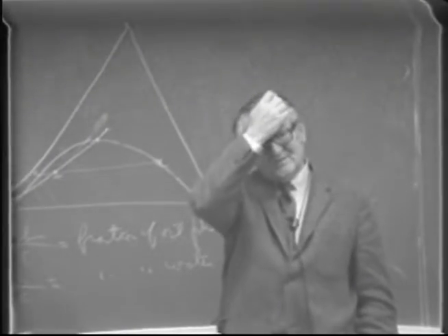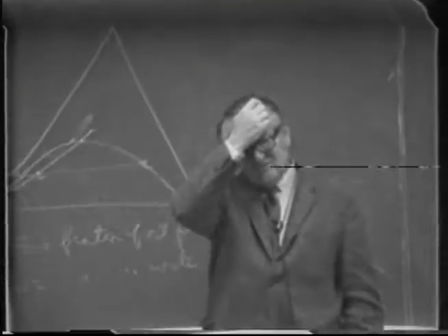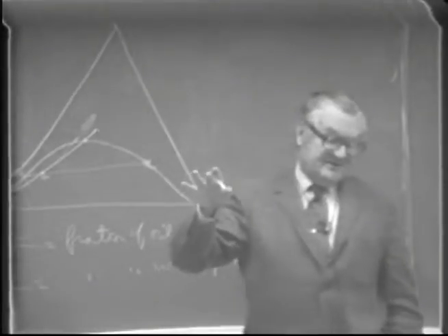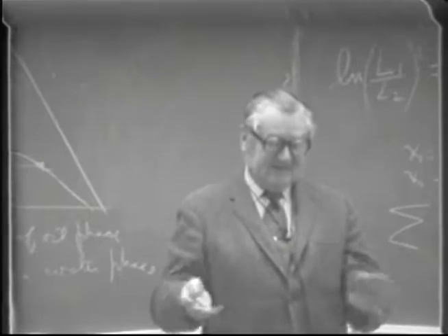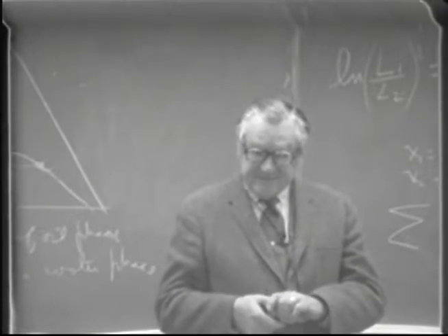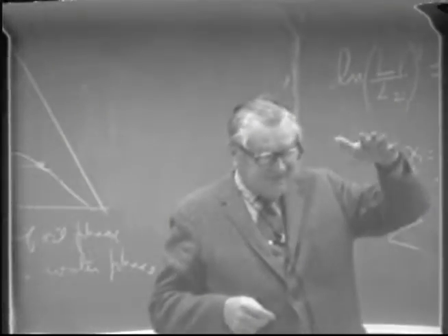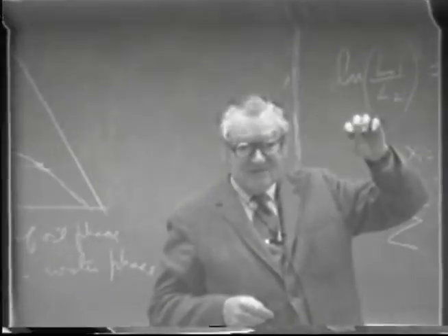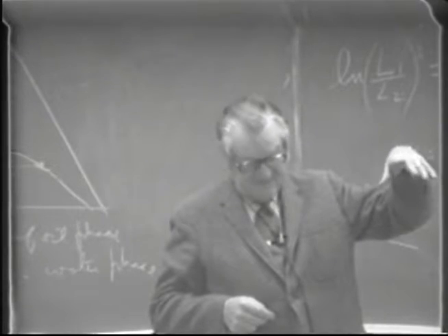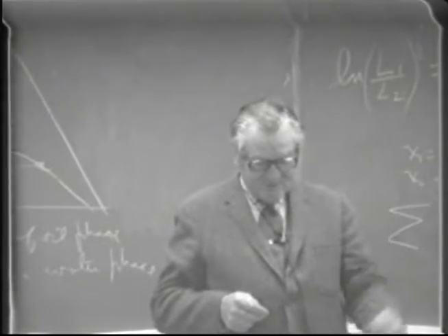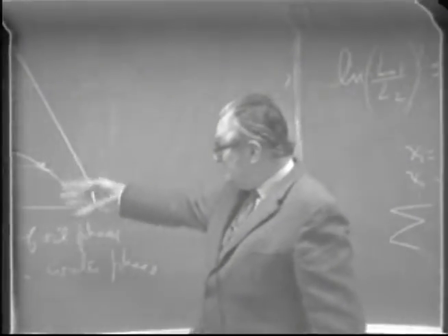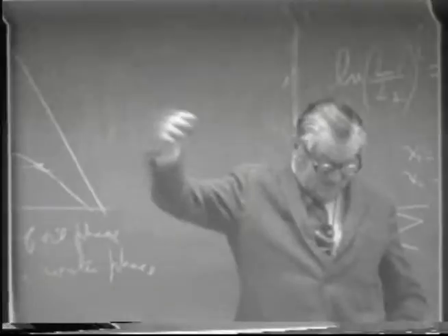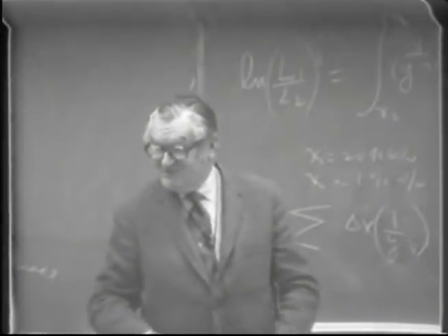When you have two phases present, even if you're considering the binary system, let's say like water and isoamyl alcohol, you'll have a lighter phase floating on top, but that'll have some water dissolved in it, but it'll be mostly isoamyl alcohol. The bottom phase would be mostly water, but there'll be a little isoamyl alcohol dissolved in that. Here, where it's being modified somewhat by the ethyl alcohol, which acts as a solvent for both, so it increases the solubility, as that curve indicates.